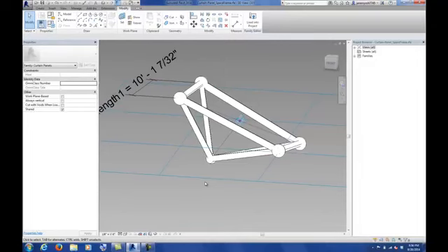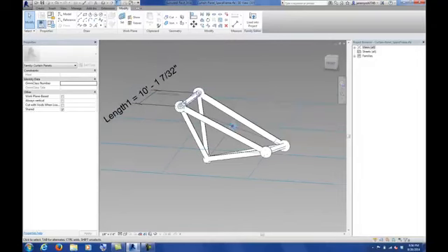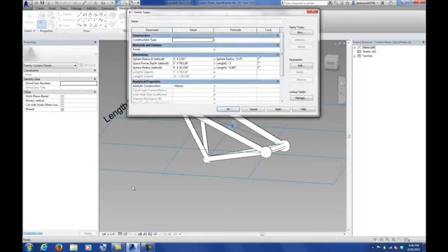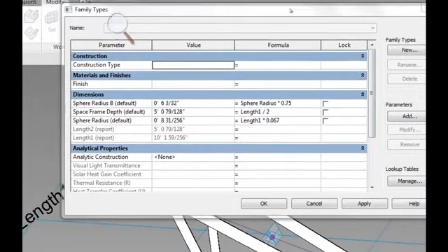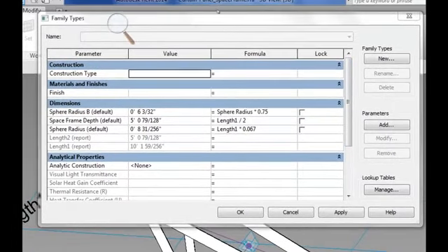So for now, just go ahead and make a length 1, make those spheres happen per those formulas, and then make this sphere basically scaled down to the other sphere radii. I'll zoom in at the end here so you can see what I ended up doing, and you can pause the video and see what those formulas should be, and that's all we need to do for now to get that to look right.